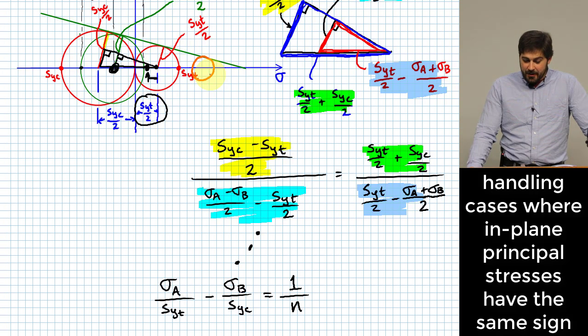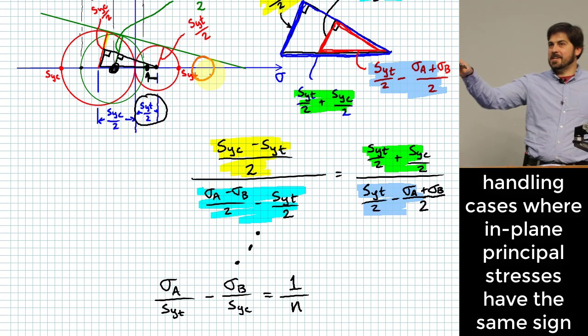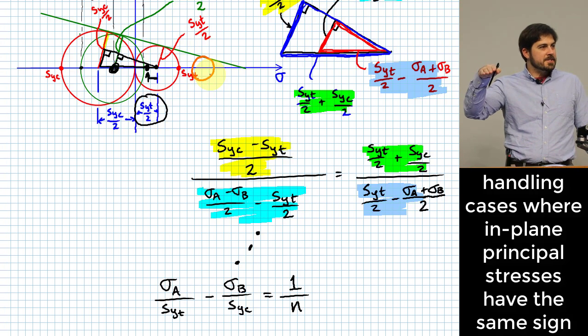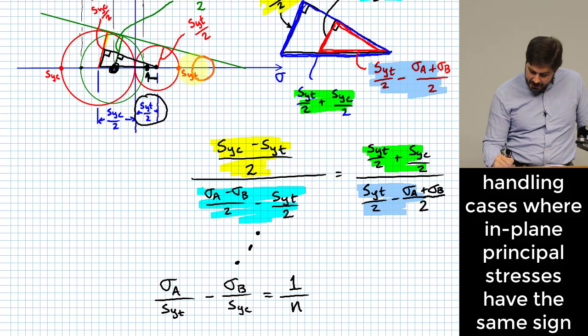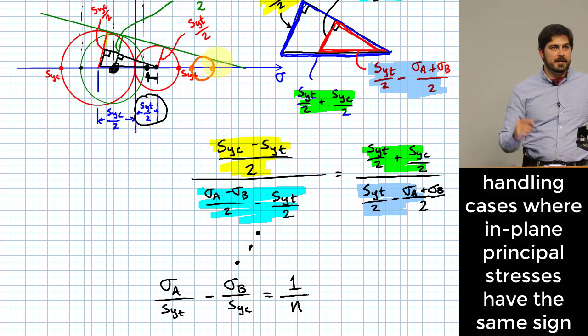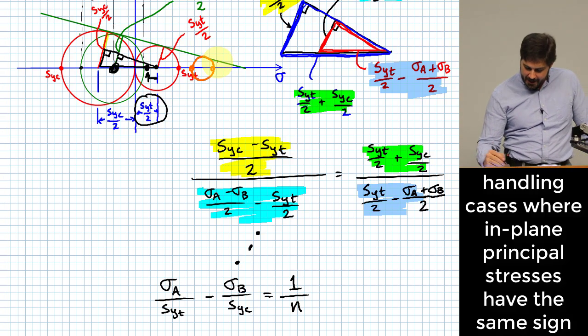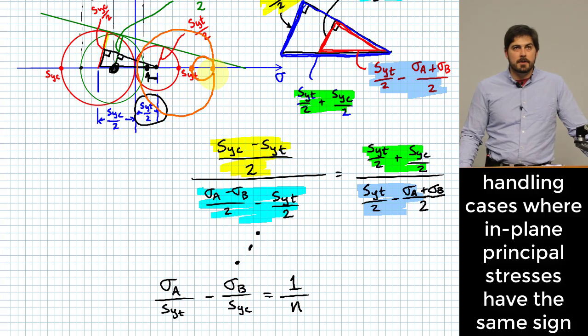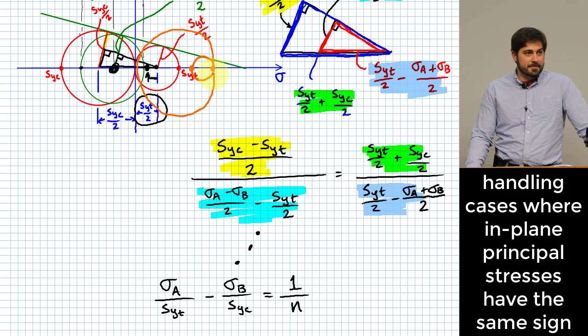Okay? Yeah, so it's tempting to think that it might be safe because it's sitting there inside of that line, right? But it's not safe because one state of stress that I have implied, once I say that this is my state of in-plane stress, there's an out-of-plane stress that's implied that does this. Back to 0. And does that stay inside of my envelope? It does not, okay?